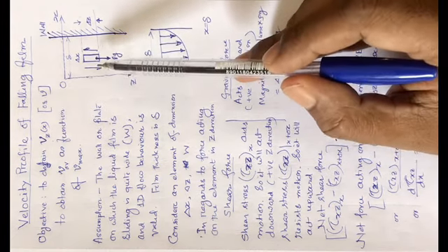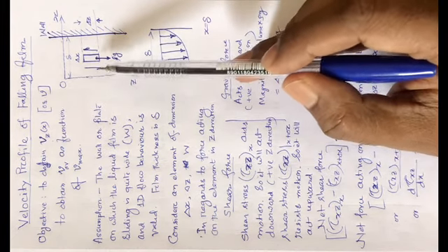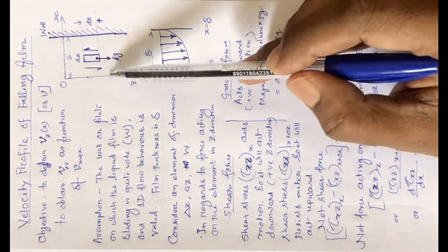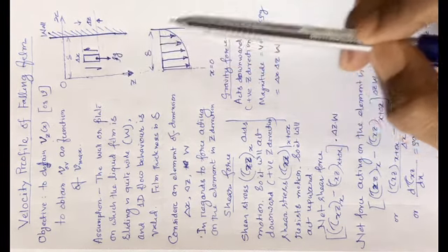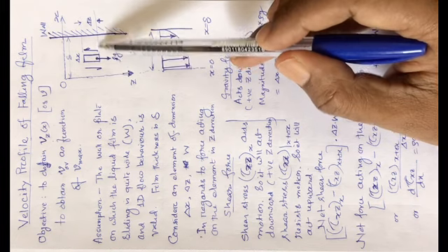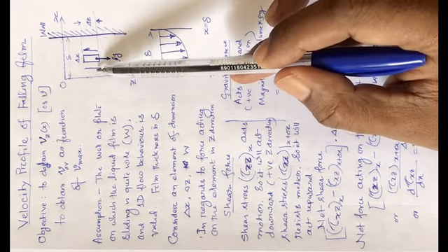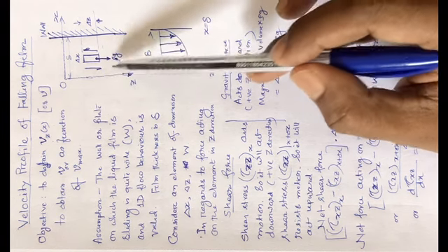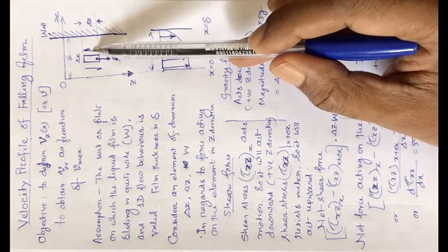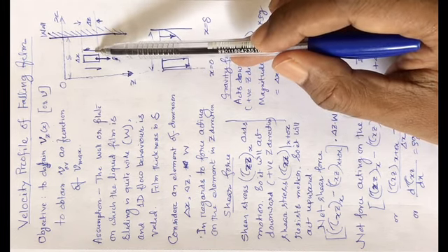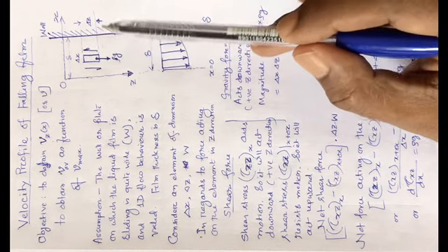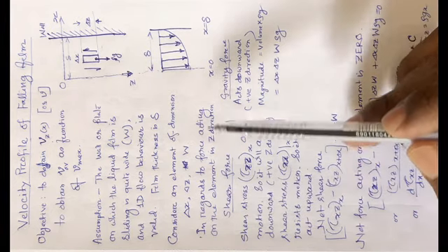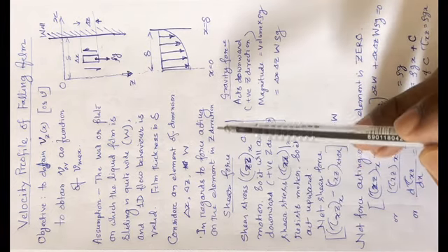Then, since it is moving downward, the outer layer of fluid in this direction is moving at higher velocity, whereas the fluid near the wall is moving at lower velocity. So the outer layer, the fluid on the left side, is dragging it downward in the same direction as gravity, and the layer of fluid towards the wall side is holding it back. Therefore we are computing the shear stress that is occurring in the z direction.